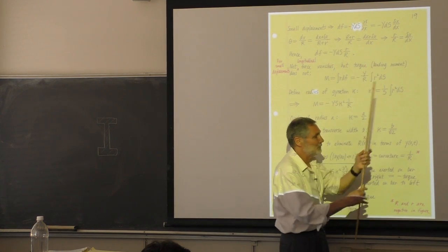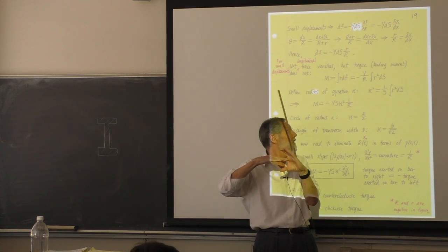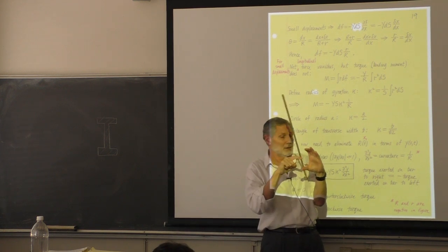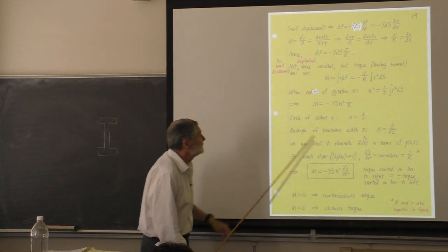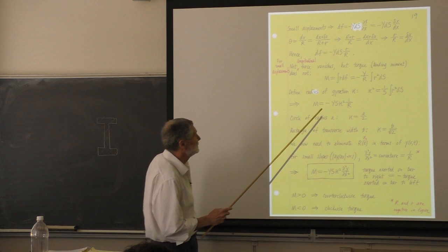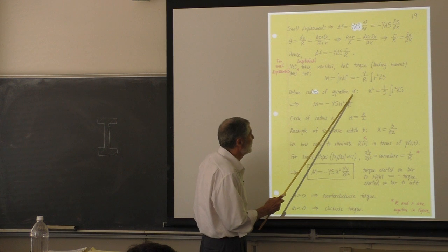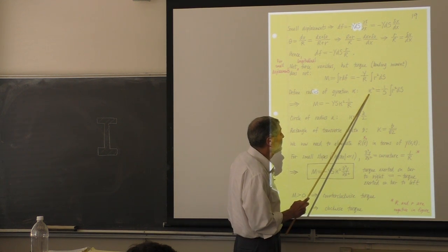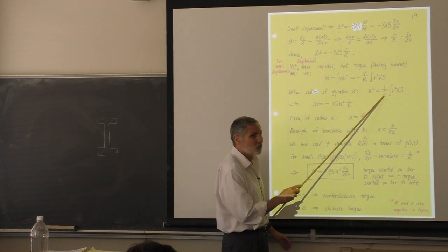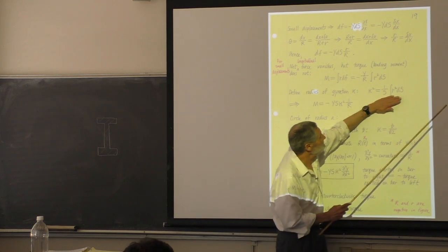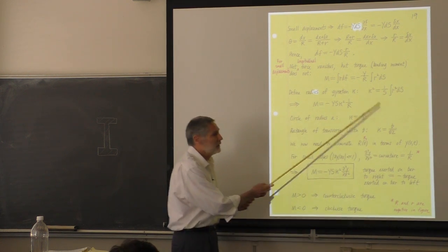What you need to do is, given your cross-sectional area, whatever it may be, if the circle is like this, and here's your neutral plane, you've got to integrate over that whole surface the square of the distance from the neutral plane. And this is sufficiently important that it's got a name. It's connected with the radius of gyration. We use kappa for the radius of gyration, and the definition is that the square of the radius is this. So it's the integral of r squared over the area, normalized to the area. You know that this is going to have dimensions of length squared, because we've divided out the area here. So that's why we have kappa squared there.